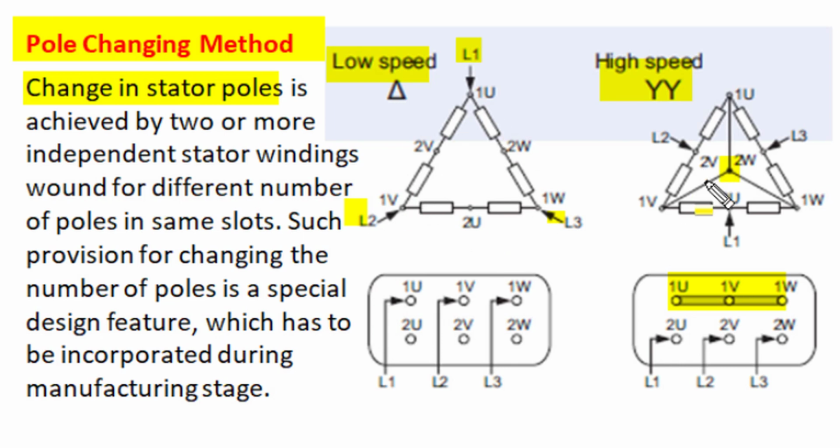So normally this method of pole changing for speed control of induction motor is rarely used nowadays, as we have a far better method of speed control by variable frequency supply, which smoothly, gradually and continuously controls the operating speed of the induction motor, whereas in this pole changing method, speed control can be achieved only in steps, not in a continuous regular fashion, and a machine with such special pole changing provision becomes costlier and has relatively inferior operating characteristics in comparison to standard single pole squirrel cage induction motors.